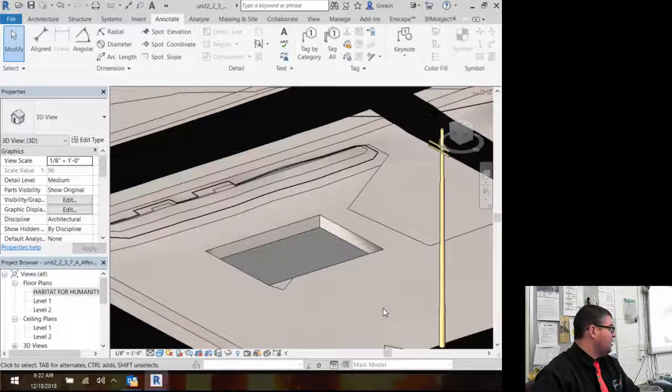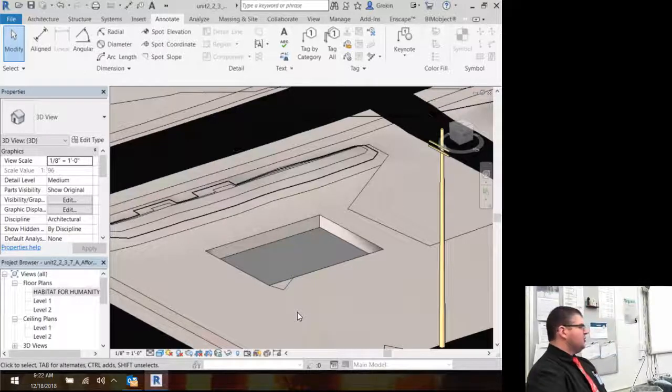It would depend. So you do 769 for your flat space. That's 4 feet below that, right? If you don't do a building pad and you just stick your house on this space, what you get is dirt filling the basement, because the zero level of your house goes wherever you put the house, and then the basement extends below that, right? Well, on the site plan, below the base level is automatically filled with dirt. That's how a site works. Does that make sense? And digging that out in Revit is very complicated after the house gets put in. You gotta have one of these building pads. It makes that very nice, sharp, clean, just spot to put a house. Gotta have one. Easiest way to do it, right here like this.